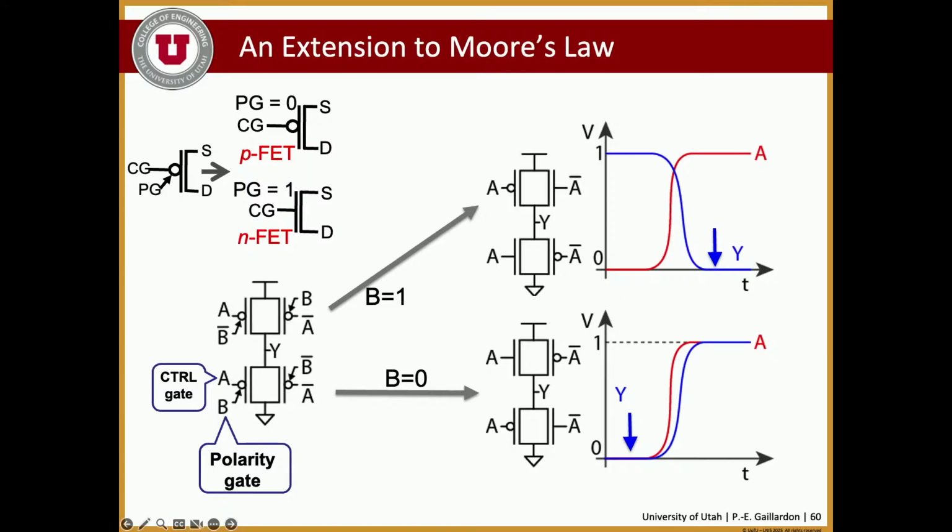But now, if we look into that, I just told you, well, we do have a programmable inverter/buffer with 4 transistors and a bunch of gates. Not super exciting, but if we try to understand what that implements, it's actually a 2-input XOR. It's a 2-input XOR realized with only 4 transistors.